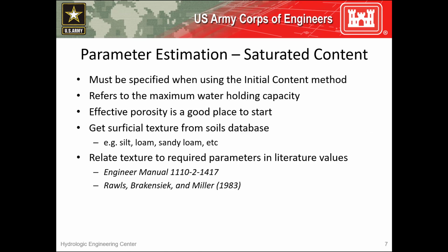The saturated content parameter must be specified when using the initial content method. However, when using the initial deficit method, you'll still need to know what this is to actually calculate an initial deficit. Now, this parameter refers to the maximum water holding capacity of the soil, and usually the soil's effective porosity is a good place to start with this parameter. Similar to the initial content or initial deficit, this parameter must be specified as a volume ratio, like cubic inch per cubic inch. Like most other infiltration parameters, I like to estimate the saturated content of a soil by relating the superficial texture from a soil's database to published literature values.